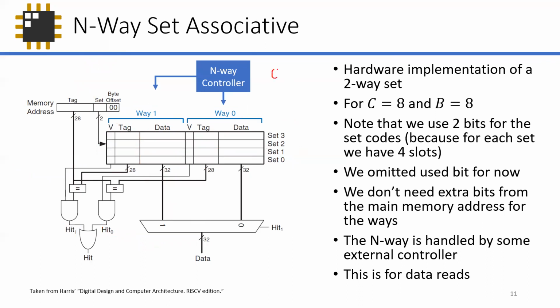Say, for example, in the case of 0, 4 and 2, 4 again, let's suppose that they were loaded already. So the data here is the 0, 4, and then the data is the 2, 4. And let's say I'm trying to access 0, 4 again. I have the bits 0, 1 for the set, which points to the set, not a problem. And then the tag bits that I'm looking for for 0, 4 are 0, 0, dot dot dot, 0, 0, and here it is 1, 0.